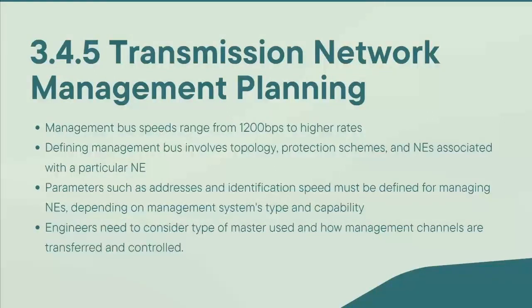So about the last slide of our point 3.4, which is about the transmission network management planning. Management bus speed ranges from 1200 bits per second to higher rates. Defining the management bus involves topology, protection scheme, and network elements associated with a particular network element. Parameters such as addresses and identification speed must be defined for managing network elements depending on the management system type and also the capacity. And the engineer needs to understand the type of the master used and how many channels are transferred and controlled.